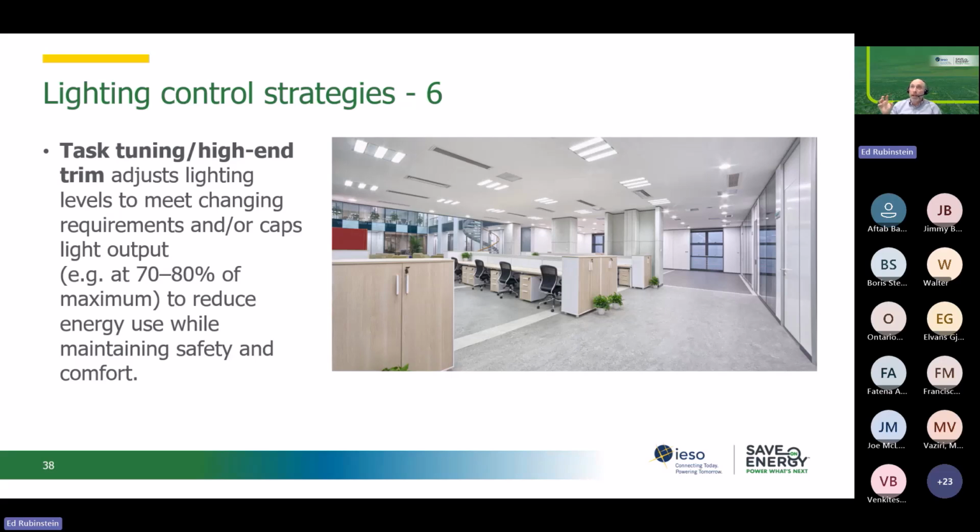Well, it doesn't matter what type of lamp you have, fluorescent or LED, the light output is going to decrease over time. So we were also able to undim, if you will, as those lamps had reduced lighting output, and extend their lifetime, right? So you can see it's a really powerful way. Obviously you need them on a single circuit here, but to control the light output for areas and by extension control your energy use.